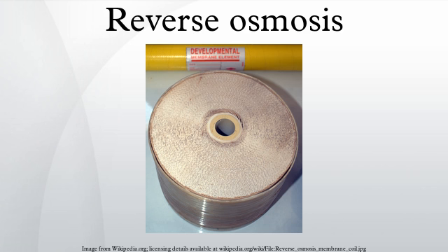Pretreatment in seawater reverse osmosis systems has 4 major components: screening of solids. Solids within the water must be removed and the water treated to prevent fouling of the membranes by fine particle or biological growth, and reduce the risk of damage to high-pressure pump components. Cartridge filtration. Generally, string wound polypropylene filters are used to remove particles of 1 to 5 micrometer diameter. Dosing. Oxidizing biocides, such as chlorine, are added to kill bacteria, followed by bisulfite dosing to deactivate the chlorine, which can destroy a thin film composite membrane.